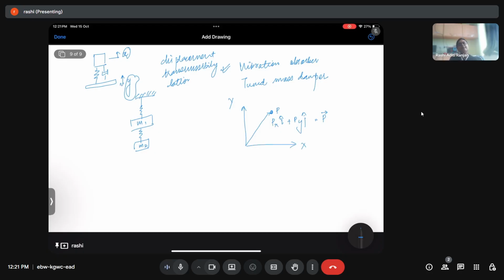A similar concept comes when the degrees of freedom of a dynamical system increases. For a two degree of freedom system, if I get two independent solutions, then I can write a general solution as a linear combination of those two independent solutions. Now, how do we find those two independent solutions? For a system, there are always going to be two eigenvalues and two eigenvectors, such that the movement in those two directions will be independent of, or decoupled from, each other.